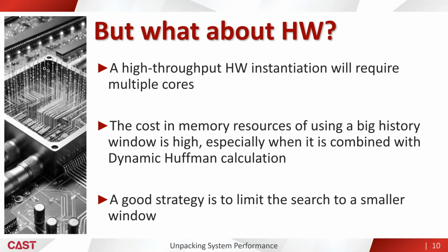Think about it. In high throughput implementations, you might need 20, 30, even more processing elements to do the compression for you. And each compression element can have 32 kilobytes of memory or more. So you multiply 32 kilobytes by 20, 30, or 40, depending on the IP throughput, in order to find the memory requirement of your application.